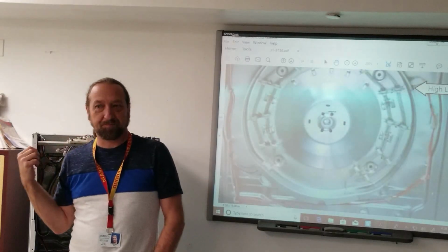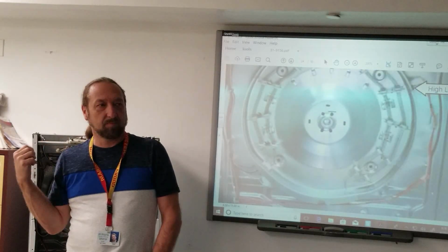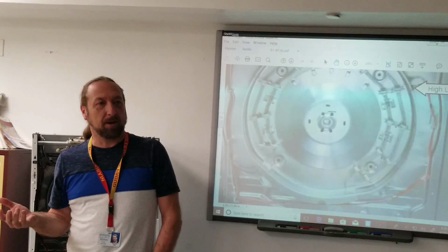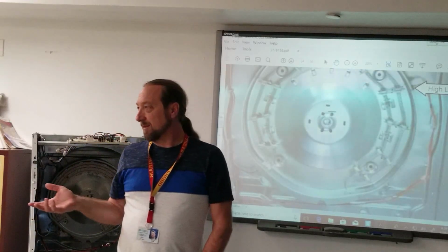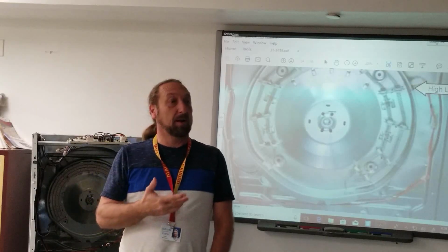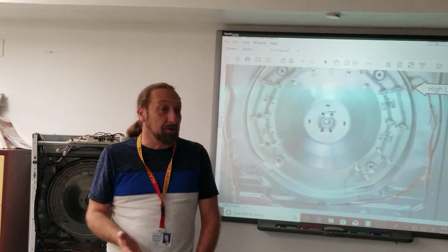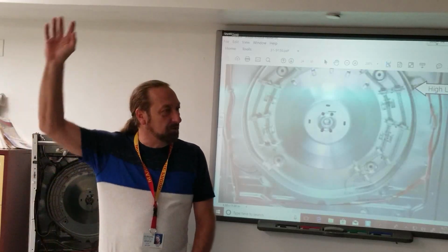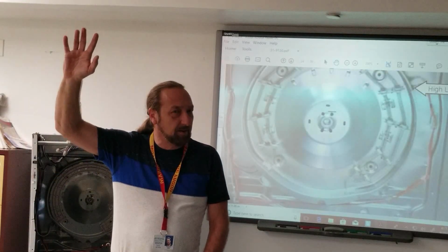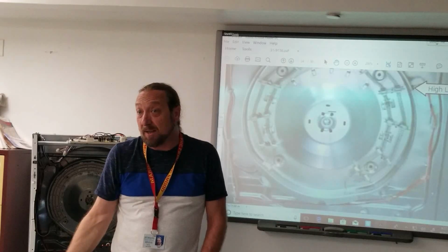So, if someone tells you, yeah, it's taking me forever to dry, you're going to take it all apart, start checking the heaters? No, not the first one. What was the first thing we talked about? The airflow. Yeah, then we're going to take the meter out if the airflow is good. If the hose in the back of the machine is blocked or the vent out of the building is blocked, a dryer could run all day and not dry.